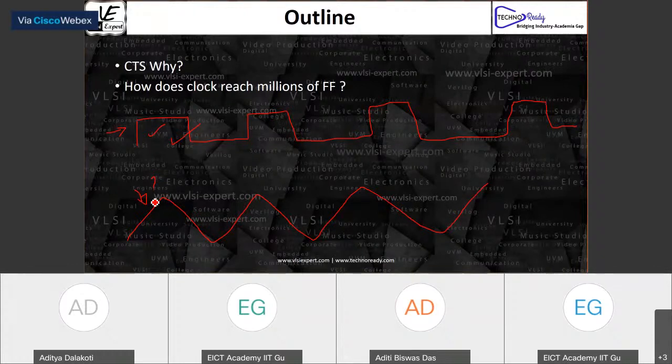Agreed, Pradyuman. Because of the differences in the rise and fall time, if we do not maintain a good slope, the duty cycle will vary, and that will lead to jitter. That is a very valid point. Completely agree there. So if you're not able to maintain the duty cycle, that eventually leads to jitter. Harish is pointing out that the clock is more prone to noise at the transition. Absolutely, that is a correct point.